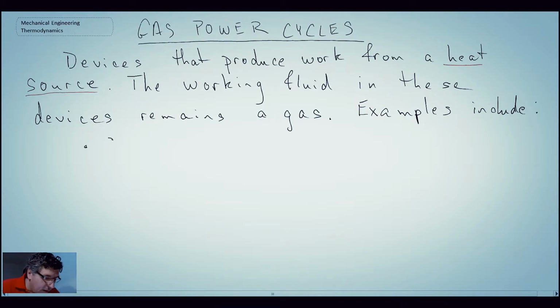We have spark ignition engines. These are engines where you have what we call a spark plug. The spark plug is a gap between two metals, and you put a high voltage across it and a spark forms. That is what initiates the combustion within our cylinder. Consequently we call those spark ignition engines, which tend to be quite popular. They're used in a lot of cars.